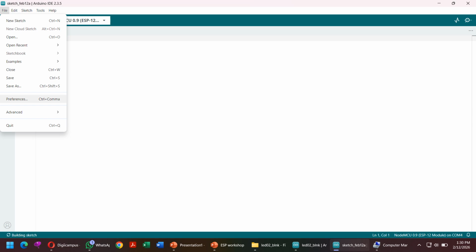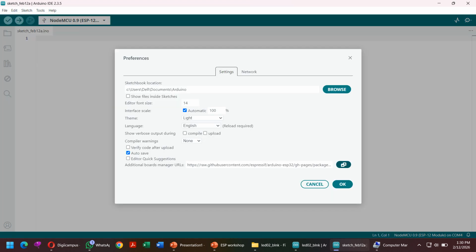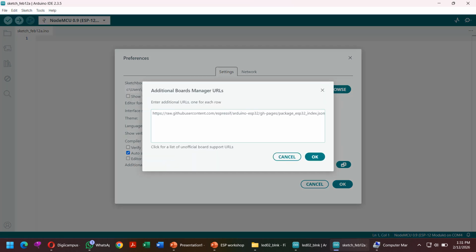Now the next very important thing you have to do is include the library. For that, go to File, and this is very important. These things you can get online. The important packages, what packages support ESP8266, will be available here. The additional packages will be on that website. So go to any Google browser, copy and paste over here. So here you can see the additional board manager.